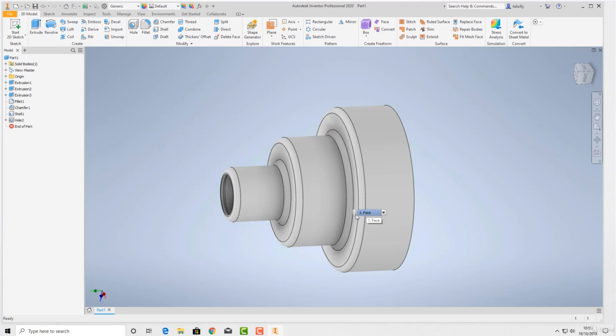But we've learnt quite a lot here. We've learnt about extruding a simple sketch, sketching on the face of existing features. So we didn't create a new work plane to create the sketch. We had one sketch here which we extruded. We sketched on the face of that extrusion, the cylinder, and we extruded again. Sketched on the face of the cylinder, extruded again. We learned to do holes, fillets, chamfers.